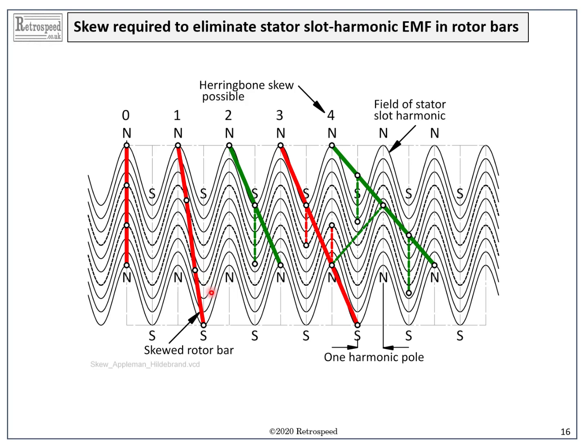There might only be a small difference between 1 harmonic pole pitch and 2 harmonic pole pitches, indicating that the amount of skew is quite critical. And for some reasons, 4 harmonic pole pitches is suggested as being the best one.